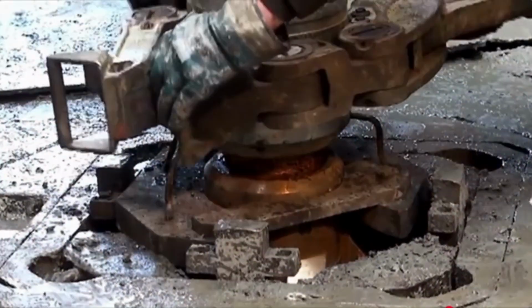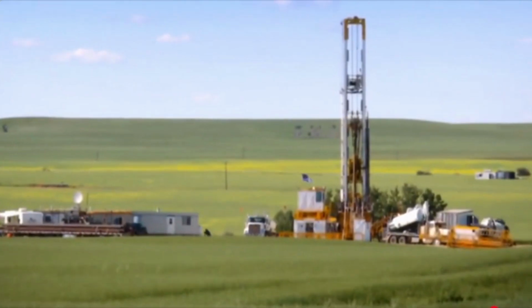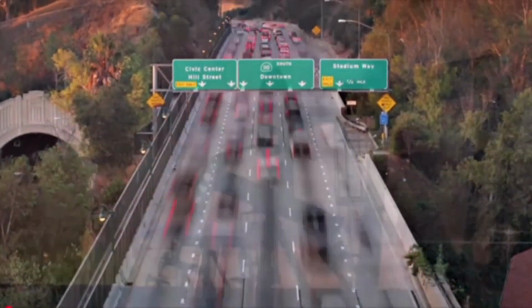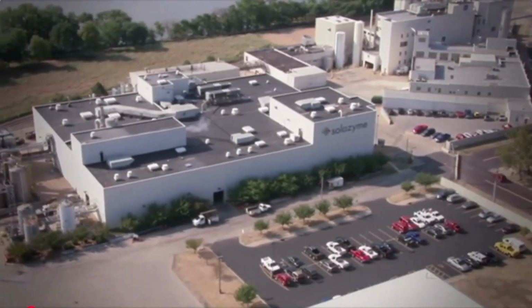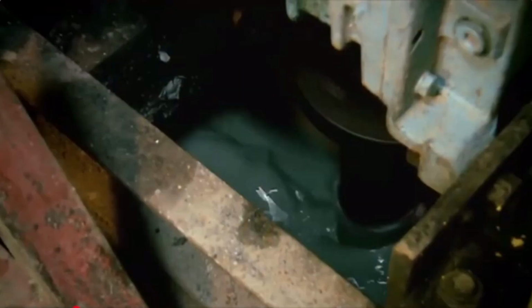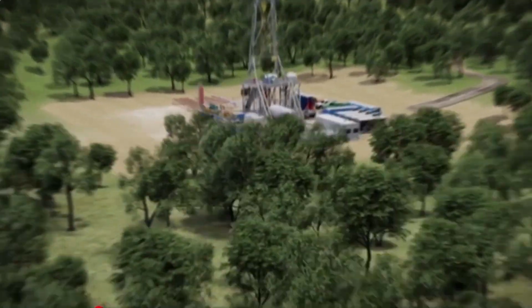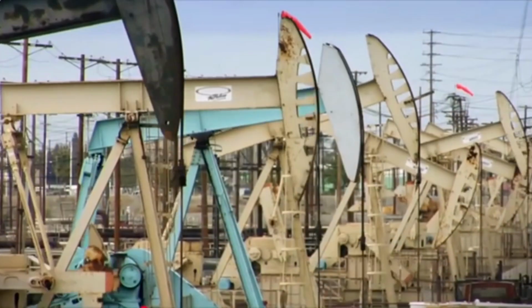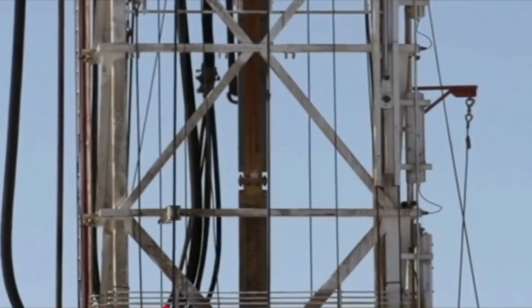In standard drilling practice, increased friction slows down operations. Mud engineers react by adding a slug of liquid lubricant. These conventional liquid lubricants seep into the rock formations, are pulled out in drill cuttings, and can lose effectiveness while circulating. What's more, lubricant loss increases drag and torque, putting expensive equipment at risk. All of this adds cost, which leaves the industry looking for a high-performance solution. To meet this need, we've developed Encapso, the world's first encapsulated biodegradable lubricant, designed so customers can drill faster, straighter, and cleaner.